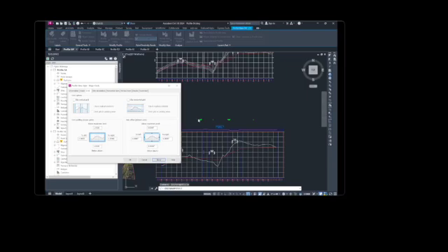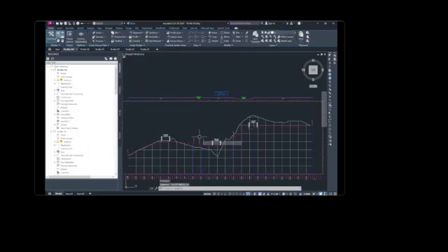Notice that in the drawing there is no one full major grid between the profiles and the profile view extent. Under grid options, select the clip vertical grid and clip horizontal grid. Under both selections, select omit grid in padding areas. Click apply. The grid is clipped to the surface profile because the clip grid setting in the profile view properties for PV1 is set to the centerline surface profile. Click OK.